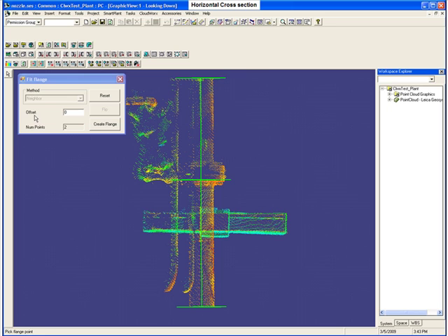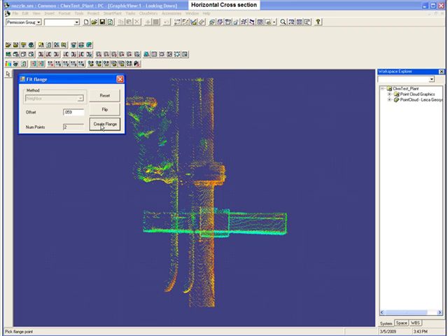And then you set your offset. I'm going to set my offset at 0.059 because that's the thickness of the flange. You know the thickness of the flange you're working with. You can just enter it there and say create flange. After you create it, you see this graphic here. The center point is this imaginary tie point, which is what you want in between the two flanges. So that's using neighbor.